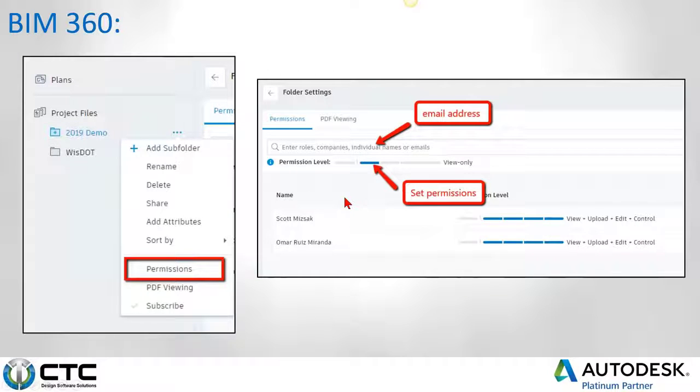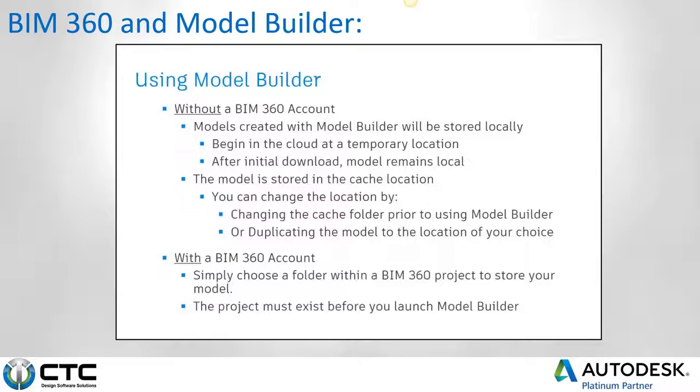At this point, they would receive an invite, and they would be able to see my model. They would be able to download my model. If they had Infraworks on their machine, they would be able to edit my model. The best thing about BIM 360 is the fact that you could actually preview the model and mark up the model without actually going into the model. I can do the preview within BIM 360. But now that I've gone through and I've created folders to store my models and then invited people the new way, I can move on.